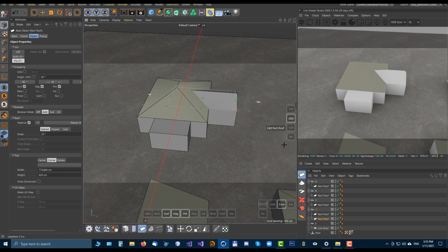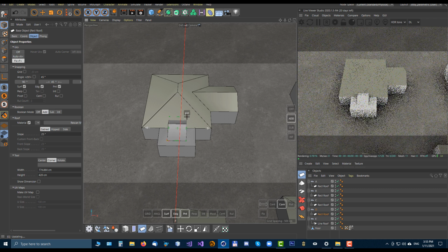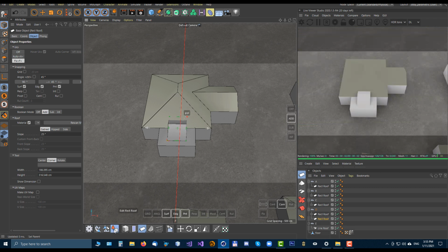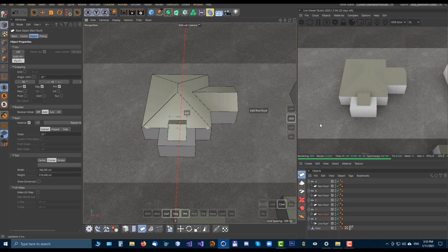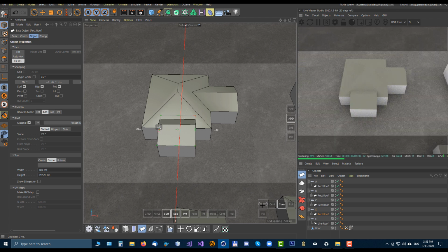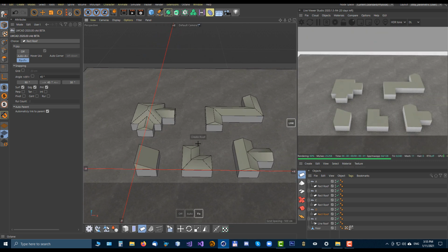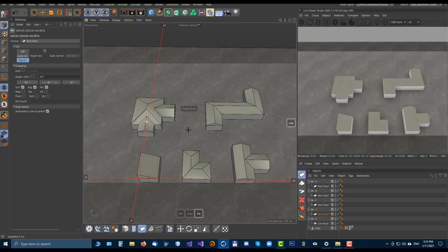But as you can see, because I'm using auto linking, the first click was on the building, so it is not properly linked, so I have to relink it manually. We want to do booleans with the roof, not with the object. And now the second, again relink, or disable auto linking. In this case it's probably better. Now use add boolean. Okay, so as you can see, this is the manual way of drawing. It is pretty fast, but very flexible.